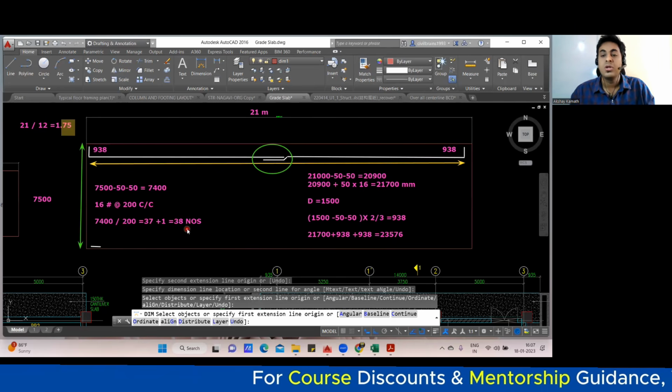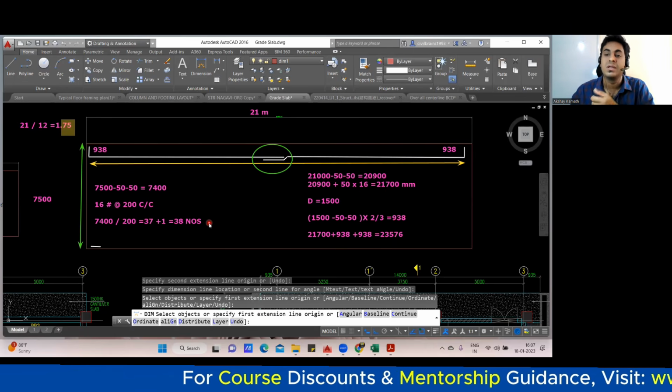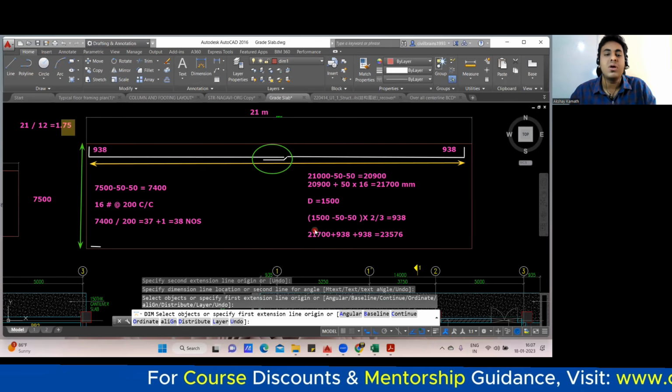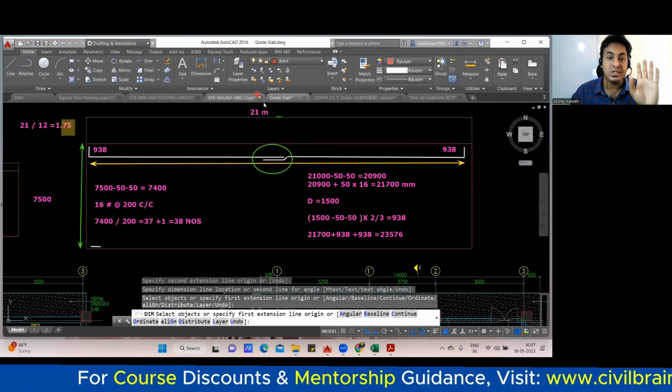You know the number of bars. You know the weight of a 16 diameter bar. Multiply all the three quantities, you'll get the weight of the steel. Simple. Very good. So this is how the BBS for the raft foundation has to be done. I hope that you're able to understand the concept.